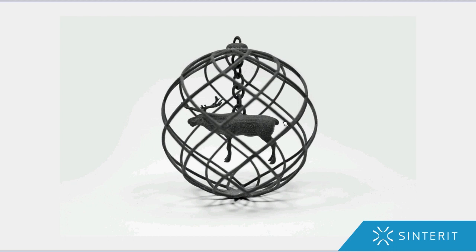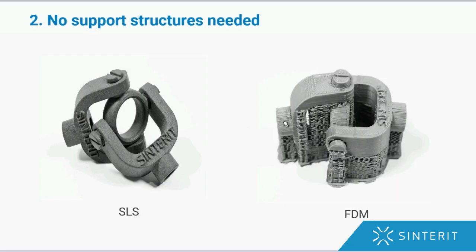You can print complex figures with interior elements as well as channels, grooves, canals, and so on. Just look at this model. It's basically impossible to print this with a standard low-cost FDM desktop printer. And now let's see what we have here. Can you see all those supportive structures? Removing them will require a lot of time and effort. With SLS, you have your prints instantly ready to use.